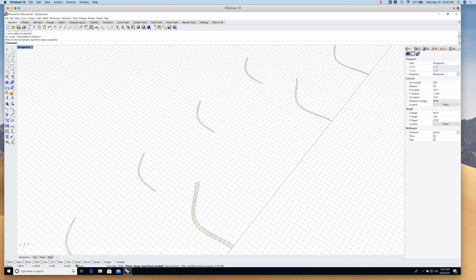0.05, right, is the key. It needs to be skinny. So you're talking just under a 1/16 of an inch, right? 1/16 of an inch is 0.0625. So 0.05 will work well. And that's where I would start. One of the things you're gonna have to do is think about that material thickness.